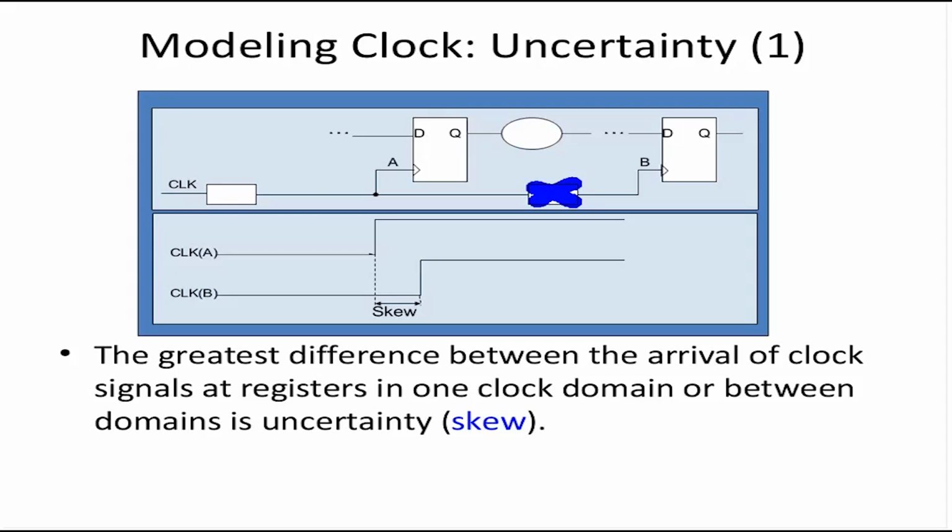In fact not even uncertainty but all the parameters, the latency, the uncertainty, the function and so on. But for synthesis purpose, it's a good practice to apply some value of uncertainty to model the clock tree effect that will come in the post layout, plus in modeling the jitter effect. So the thing to remember is that uncertainty will have two parameters in synthesis. One is the clock tree estimation, other is the jitter estimation.